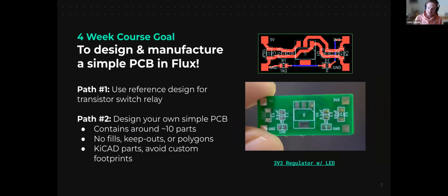So let's start first with the screw terminal here. I'm just going to type in screw terminal 01-X0103 because this one is a 3-point screw terminal. As you can see here, Flux showed me 4 parts, but I want to pay attention to the part that has a 3D model and footprint.